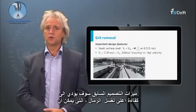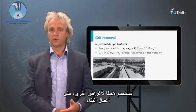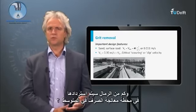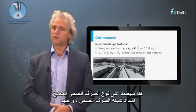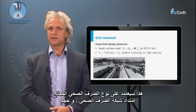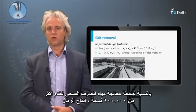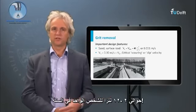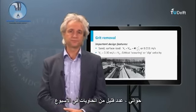The above design features will result in an efficient washing of the sand, which can subsequently be used for other purposes, like construction works. How much sand will be recovered at an average STP? Now, this will depend on the type of sewerage applied, the extent of the sewer network, and the size of the area served. For STPs treating the sewage of more than 100,000 inhabitants, the sand production is about 2 to 12 liters per person per year. So, a few containers per week.